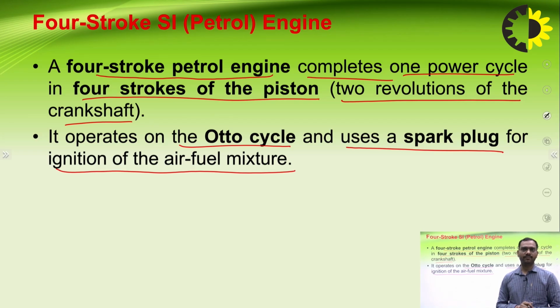It consists of 4 processes, in other words, suction, compression, expansion and exhaust. And in this engine, one power cycle is achieved in 4 strokes of the piston or 2 revolutions of the crankshaft.